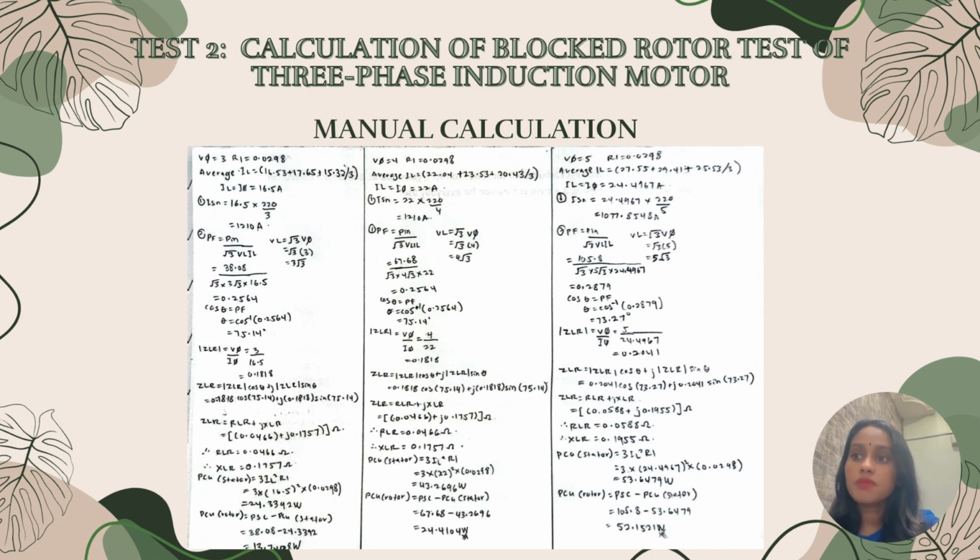13.7408 watt. So okay, while for the middle part, input power IL is equal to 22A, S is equal to 1210 VA. So the power factor and angle, power factor is 0.2564 and the angle is 75.14. Impedance Z is equal to 0.1818 with a cos 75.14 angle plus J sin 75.14, equal to 0.466 plus J 0.1757.